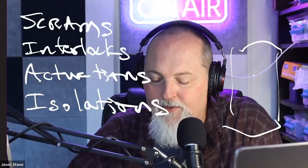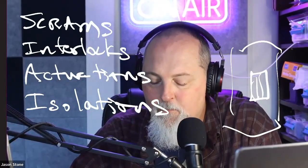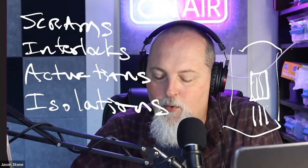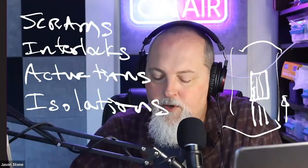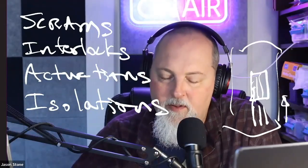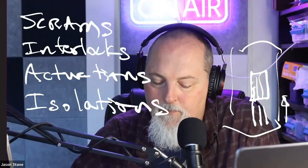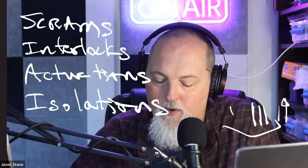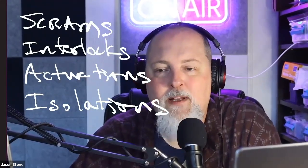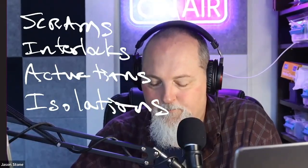This is a reactor pressure vessel, and inside there in the middle is this core, and this is where all the fuel is. And then we have control rods down below it, and these go up into the core to shut down the fission process, to absorb the excess neutrons. One of the things that's important to understand is that we can't actually completely shut down a reactor to where there's no fissions happening right away.